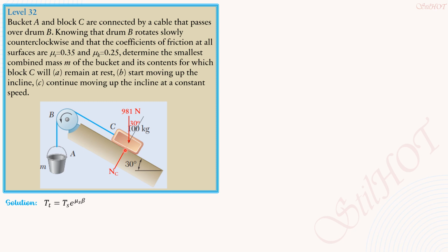And therefore, the friction will depend on the information and condition here. So I'll just put it up or downward. And it is mu, which may be mu sub s or mu sub k, times n sub c, depending on our analysis here, which will be explained later. So since the couple applied for this to move is to rotate this counterclockwise, therefore, by principle, this should be the tight tension for all cases. And this is the slack tension, T sub S.